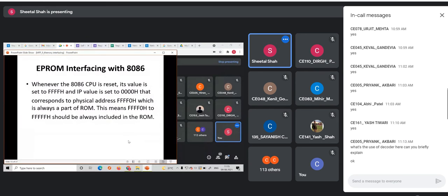Whereas if it is already stored in the ROM at a particular address, then whenever you start your system, the CS as well as IP would directly be pointing to that particular address, where it would execute the program to check the devices or the interfaces which are connected to your system. All of you are agreeing to this? And that program should be in the ROM. Then only it would be permanent, isn't it? Or else it would be lost.